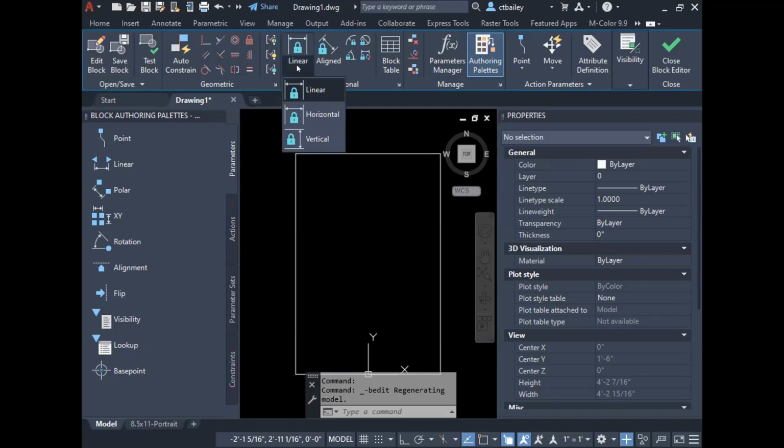Yeah. One of the assignments was that long bracket with the arcs on each end, and you can set it like 96 inches wide using one of these linear dimensional parameters. Something that already exists that you apply that to, is that what that is? That's right. Yeah. And it's interesting that it's not exactly dynamic yet. So that's why the dynamic block is just one step above parametric drafting.